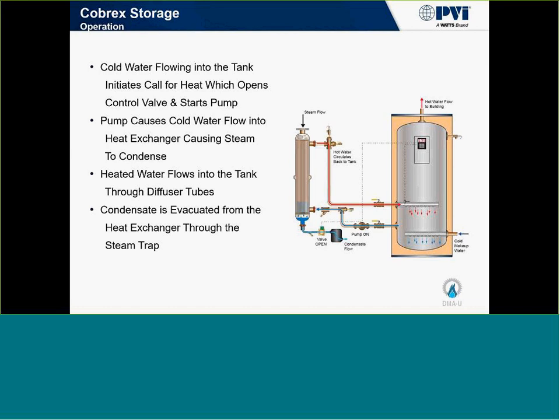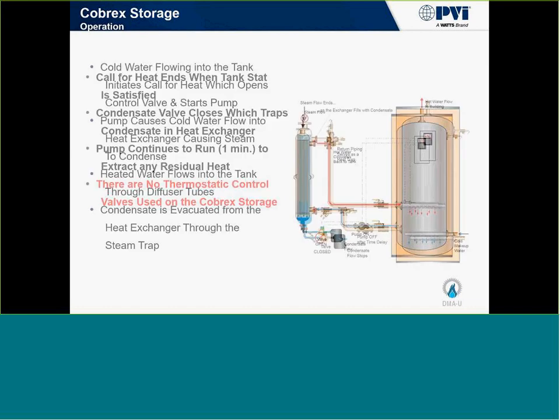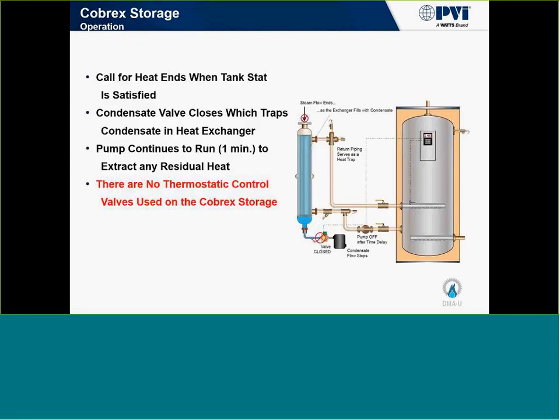With this, you would be able to control the temperature inside the tank just like you would with any other water heater. It just depends on how long we want to run that pump and how much hot water we want to throw into that tank through the baffle diffusers. So the nice thing about this is there's no thermostatic control in it. We just have a T-stat and a pump, which, like I said before, is going to allow us to raise or lower the overall temperature and outlet temperature that we're putting out into that building.